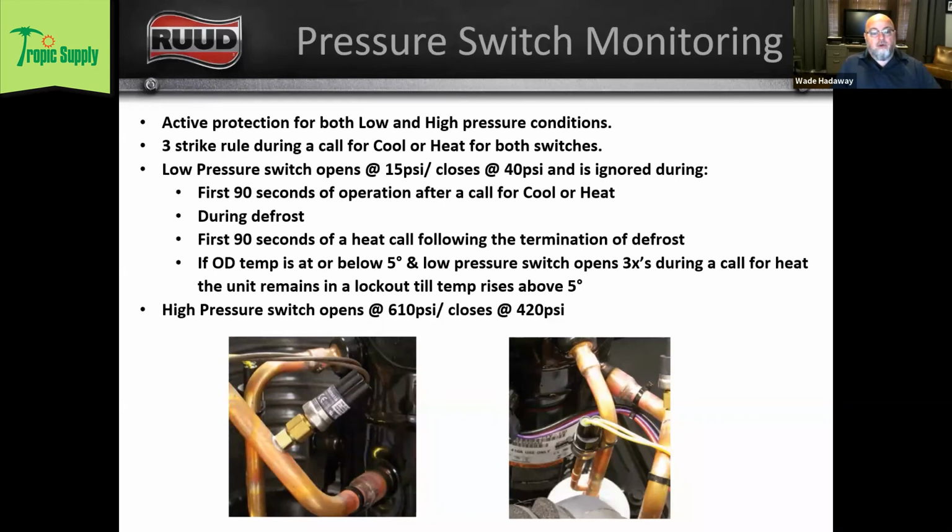And if the outdoor temp is at 5 degrees or below, and the low pressure switch opens 3 times, it's going to lock the unit out until the outdoor temp rises to 6 degrees or more. I don't see that being that big of a problem for anybody on this call today.